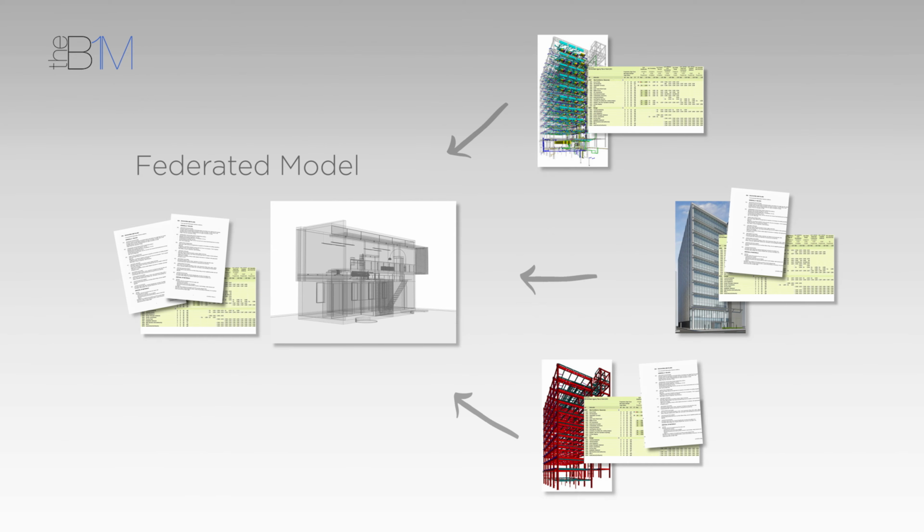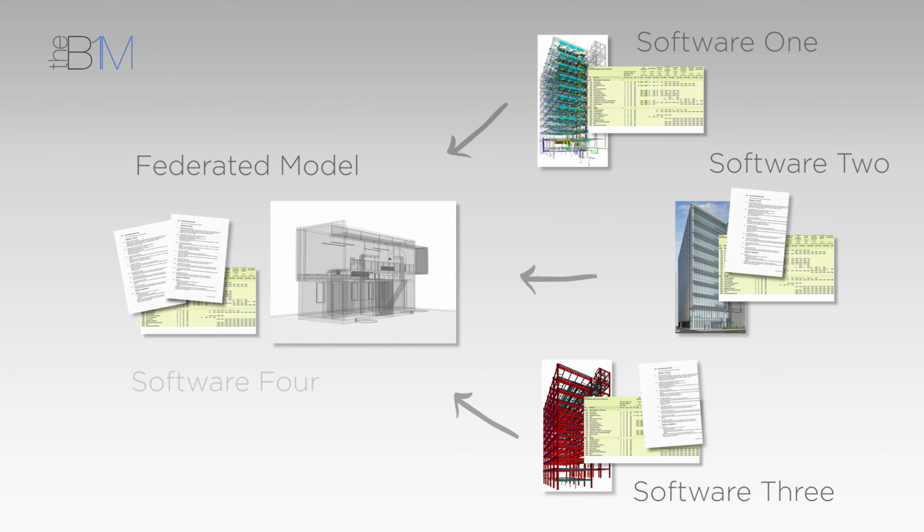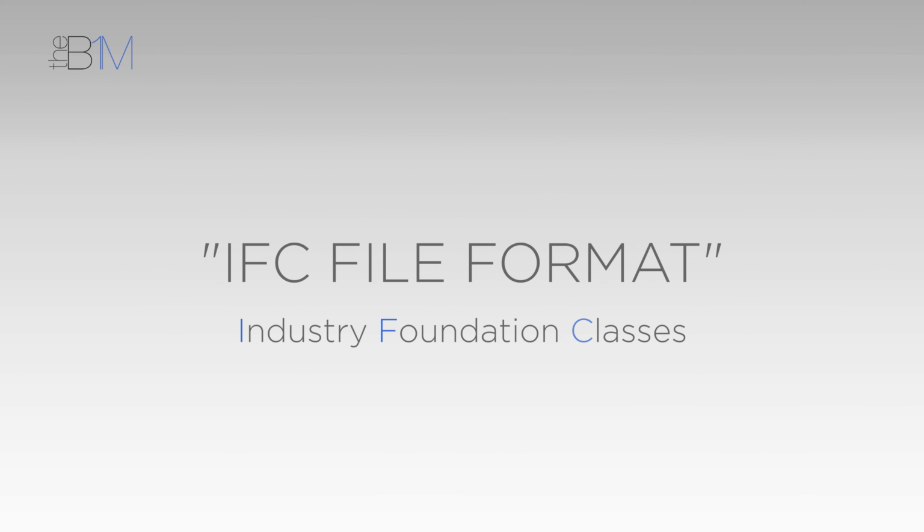For example, if your 3 different designers create their models in 3 different types of software, and then federate them in a 4th type of software before sharing them with you, you need to ensure that files can be exchanged, opened, viewed and interrogated easily between all the platforms and that pieces of data are not lost or corrupted in the process. The Standardized Industry Foundation Classes, or IFC file format developed by Building Smart, has helped hugely with this. Most model authoring software tools give you the ability to save things in IFC format, a common language that all other software types can read.